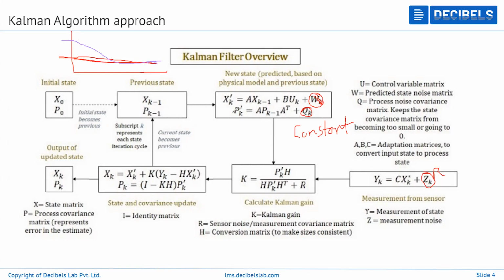It is because of the constant noise, Q and R. Whatever values we fed in initially won't be updated; the same constant values are fed here and here for every cycle of calculation or estimation. That is one of the drawbacks of the plain extended Kalman filter.